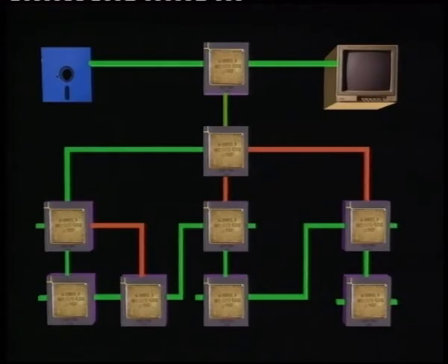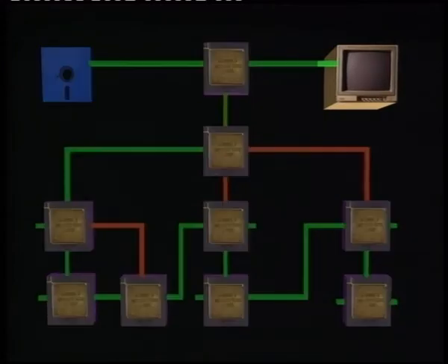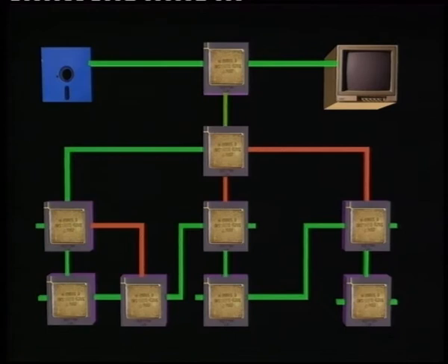The slave G task runs on transputer TG and manages the B007 graphics board. This involves setting up the lookup table and displaying one of the 2 images stored in either video buffer 1 or video buffer 2. Each of the tasks running on transputers T0 through T7 processes a single strip of the image and in some cases concurrently switches other strips of the image to other slave tasks in the network.